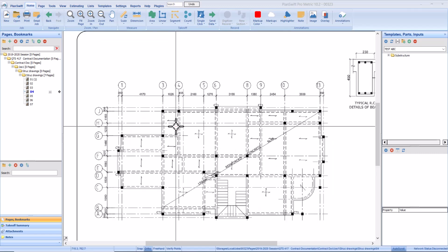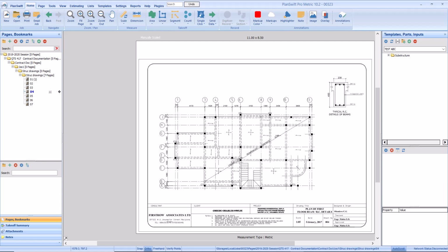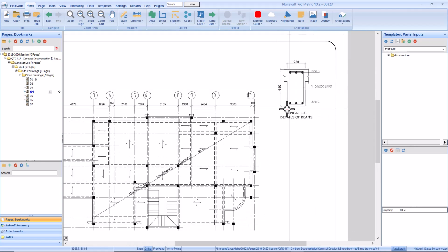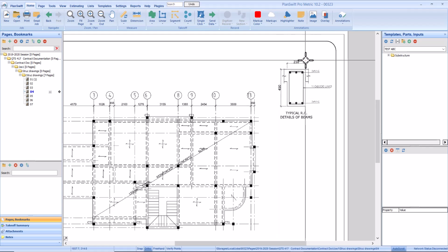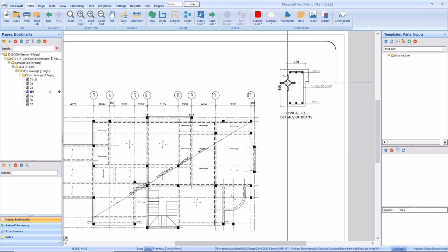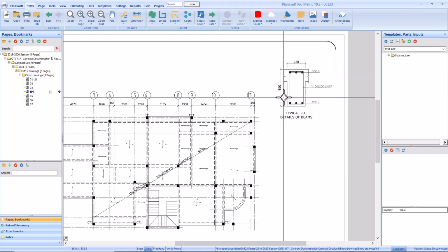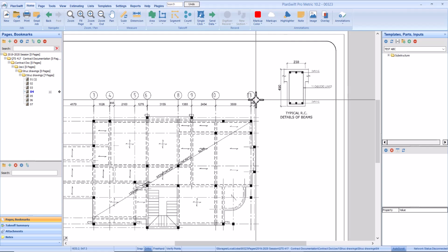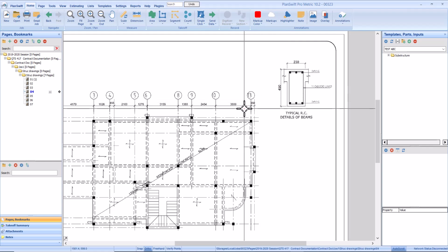This particular one is just one type of beam, and you can see the part cut out, which can be referred to as our section, showing us the depth of both the beam and the slab. Our slab in this case is 150, and if we subtract 150 from 450, we have 300. That means the thickness of our beam is 300.